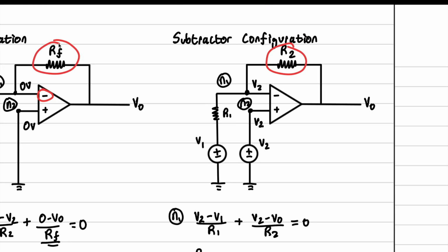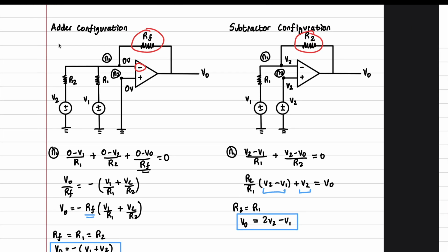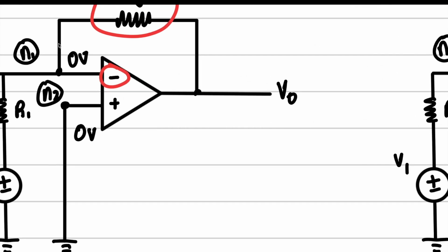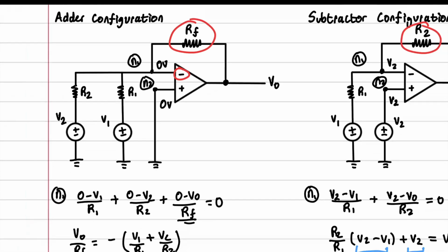So that's it for op amps. One more thing I want to highlight is the fact that you are not going to draw a node at V naught. Okay, that is just a mathematical thing. Like just don't draw a node here. It'll greatly simplify. You're just adding an additional node to your equations for no reason.